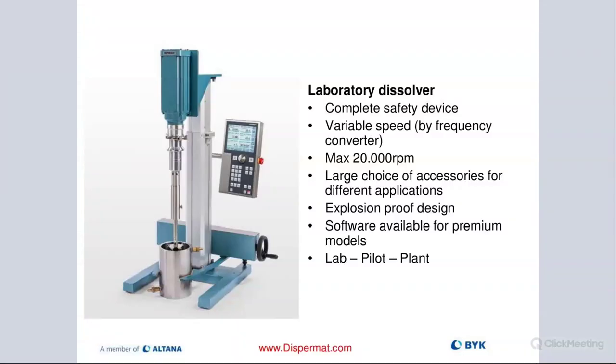And that wheel right there on the right side of the machine is actually used to tighten the container clamp or loosen it. So there's a sensor back in here that measures the pressure and ensures that the container is always fully clamped. If for whatever reason somebody were to open that during operation, the machine would automatically power down and you wouldn't be able to run it.